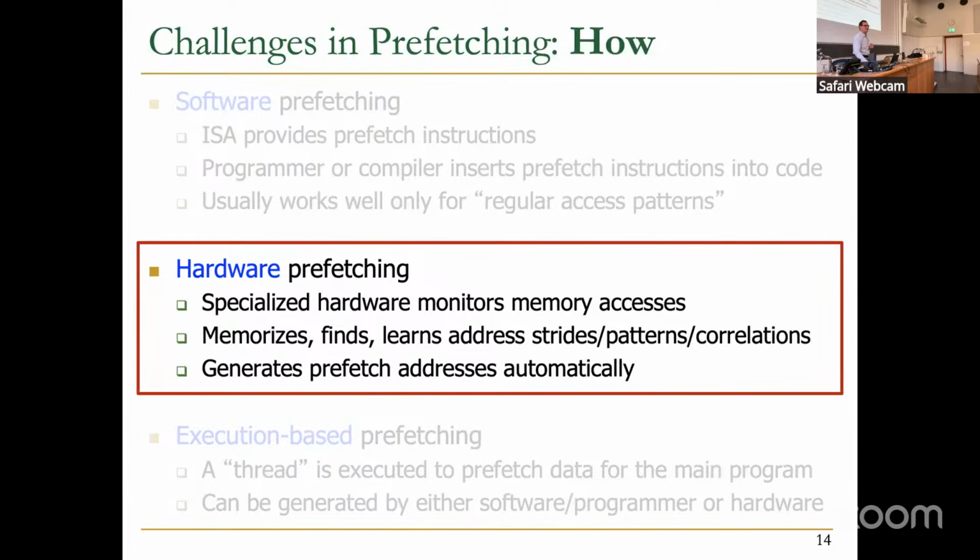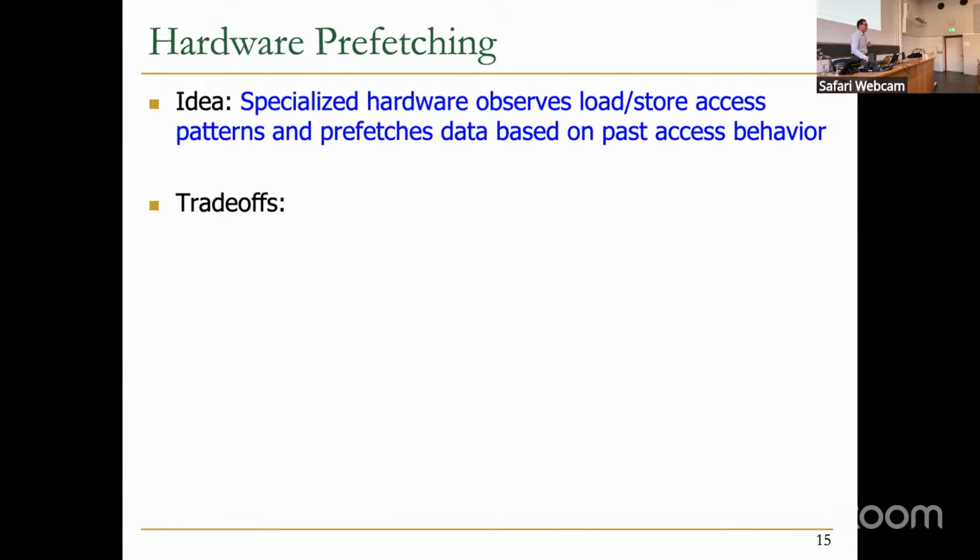Okay, so here we're going to design specialized hardware that observes load store access patterns or cache miss access patterns and prefetches data based on past access behavior. And we've seen some access patterns last time. Now we're going to see how to capture them in hardware.